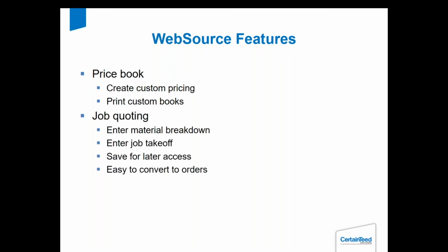Job quoting. You can do job quoting by either, if you know the breakdown already, you can enter the material directly into WebSource and it will give you the quote for the materials you need. If you don't have a breakdown of the materials, you can go in and, using our CertainTeed estimator, put in the layout of the job, and then the estimator will break down the job into the number of sections, end post, line post, corner post, and do that for you.